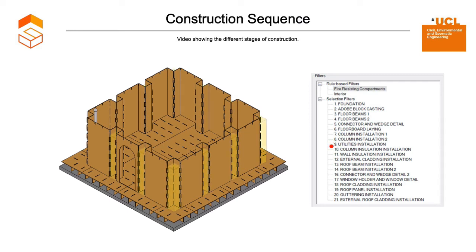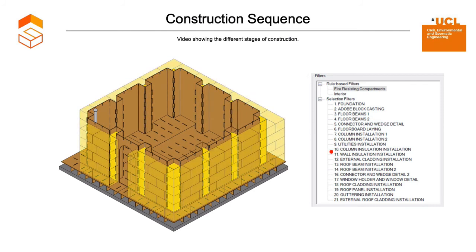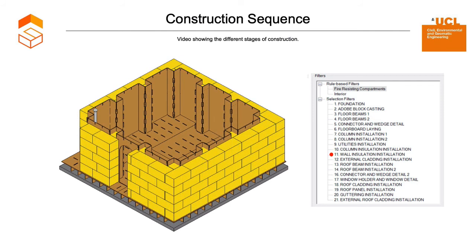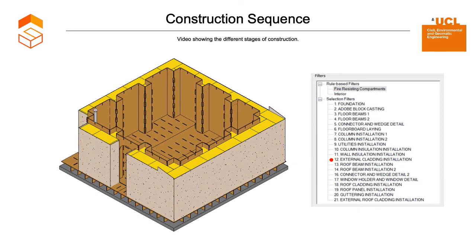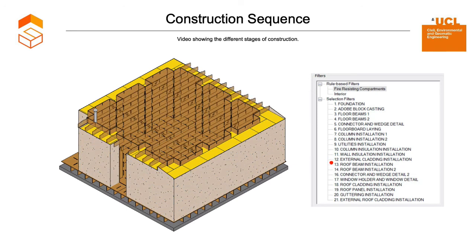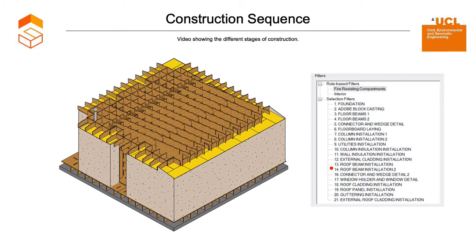Two beams are joined using a connector and wedge. This procedure will be taught during construction team training. Utilities installation consists of installing the water butt, stovepipe, and external ladder. The construction of the walls includes installing bamboo inside the voids and pouring cement to form a bond with the insulation blocks. The roof system beams and joints will be constructed in a similar manner to the floor system.